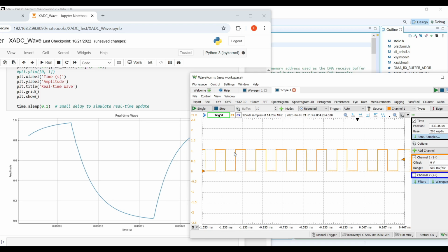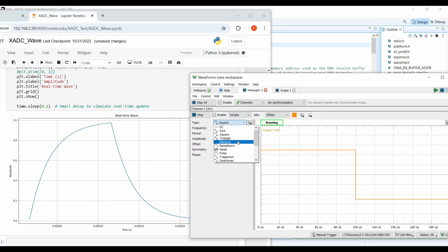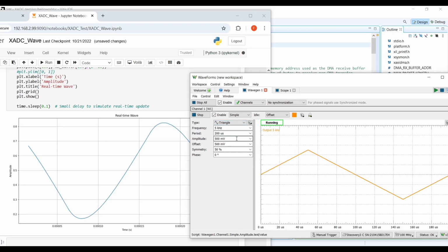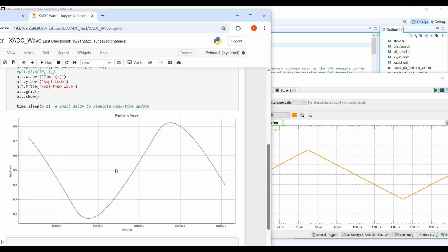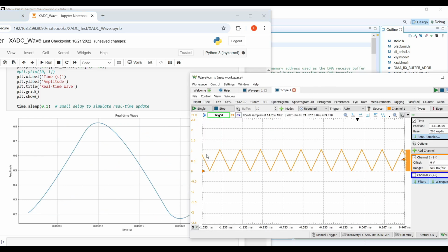However, the Analog Discovery oscilloscope captures the pulse signal without any issues. Unfortunately, when testing other waveforms, such as sawtooth or triangular signals, the XADC also fails to capture them accurately, as their rapid transitions are filtered out. Again, here the Analog Discovery oscilloscope samples the signals perfectly. That shows the input signal has good quality.